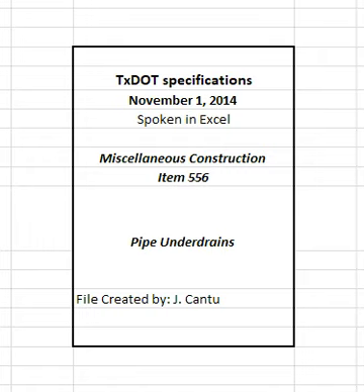3. Construction. Begin excavation of the trench at the outfall and proceed toward its upper end, following the lines and grades shown on the plans or as directed. Hold the minimum horizontal limits of excavation for filter material to the dimensions shown in Table 3 or as shown on the plans. Table 3. Minimum horizontal limits of excavation for filter material.